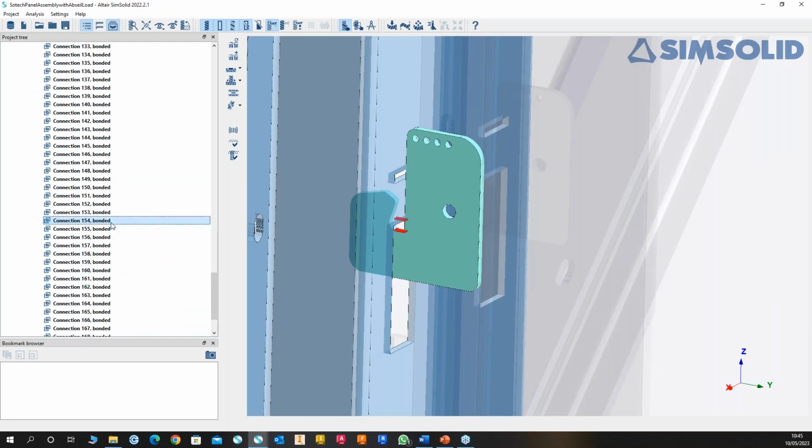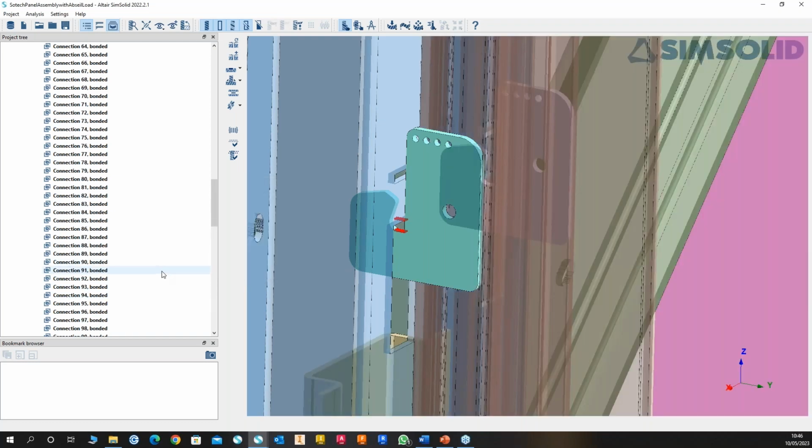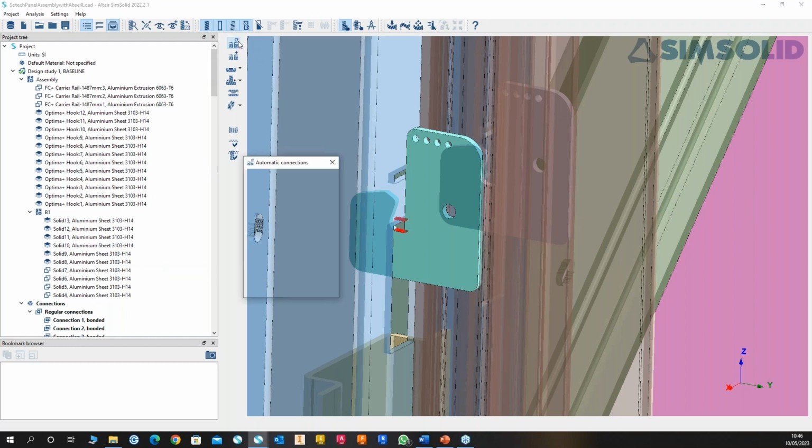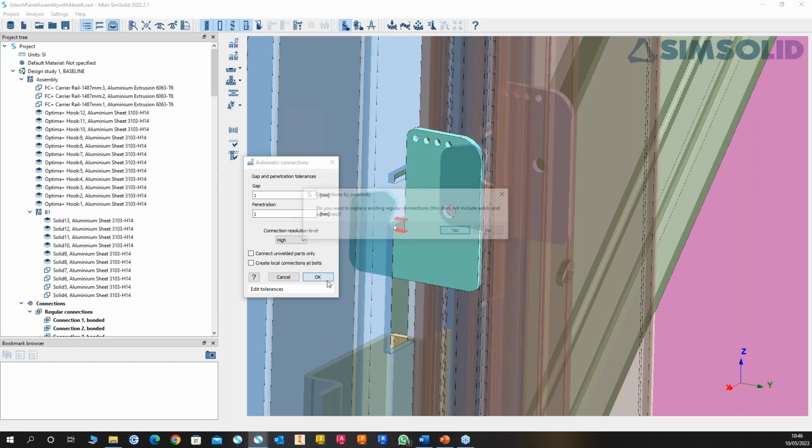So that's bonded. If I right-click on that one and choose edit contact condition, you can change it. You can disable it, or change it to separating and closing, which means it can come close to the actual midpoint support, but not go beyond it. Typically they don't come really close; the displacement tends to be very low at this point. So I'm going to disable that, but because I'm going to disable them all, I'll rerun this connection and set that back to 1.